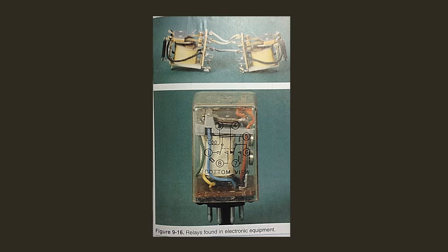Looking through a parts catalog, you will notice various relay designs, Figure 9-16, for example. When choosing a relay for a special purpose, there are several things to be considered. Three important considerations are the number of contacts, the amount of current the relay must carry, and its de-energized position. Well-designed relays have points made of silver alloys, tungsten, or other alloys. A relay can be chosen to open or to close a circuit.